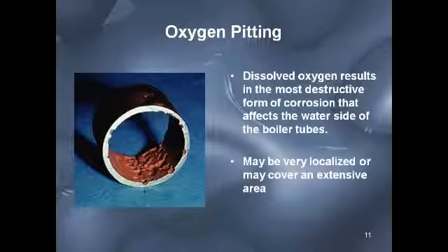One situation I always like to note is that in new boilers, or in one which has been drained and refilled with untreated water, air bubbles will form on the tubes. In a very short time, pits develop under these bubbles. Penetration as high as 50% of the tube wall has been known to take place in one stagnant period of 2 weeks. So once these pits form, they proceed rapidly even under operating conditions.